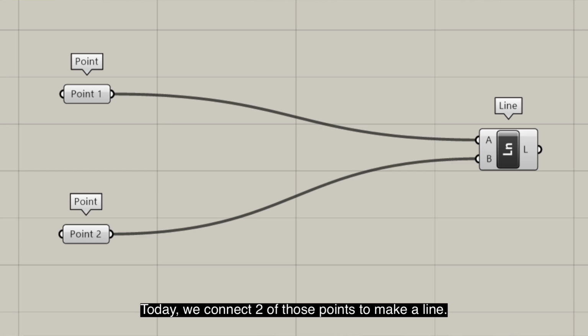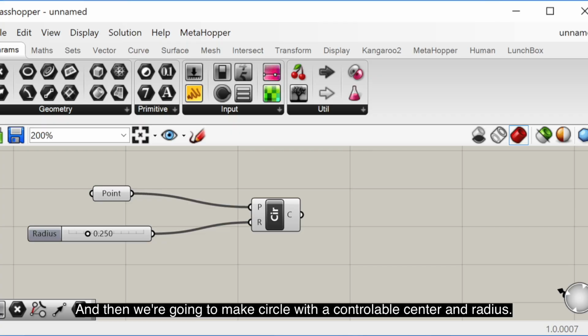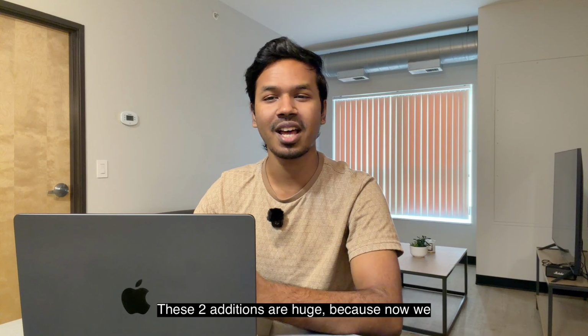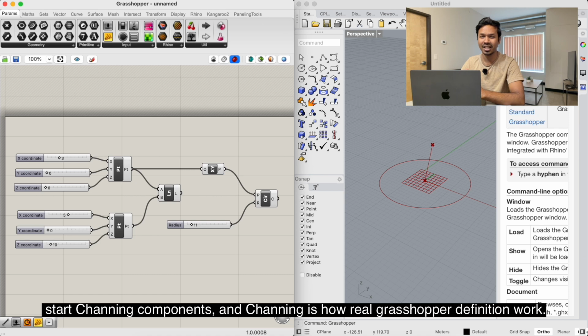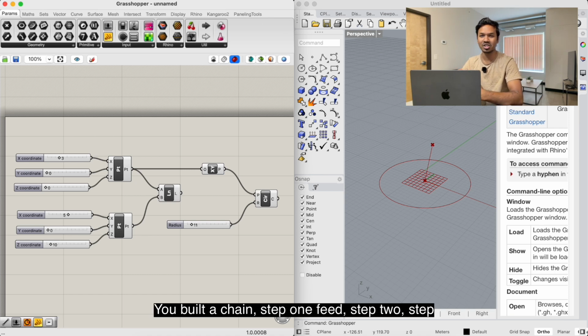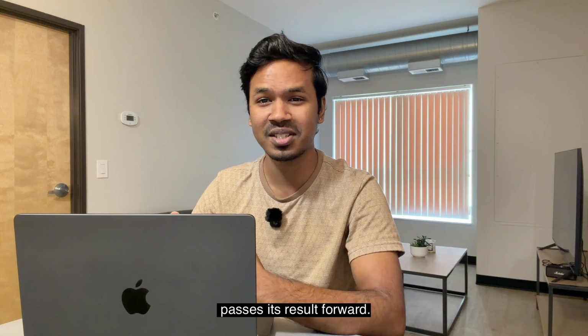Today, we connect 2 of those points to make a line. And then we're gonna make a circle with a controllable center and radius. These two additions are huge because now we start chaining components. And chaining is how real Grasshopper definitions work. You build a chain, step 1 feeds step 2 feeds step 3. And each component does one job and passes its result forward.